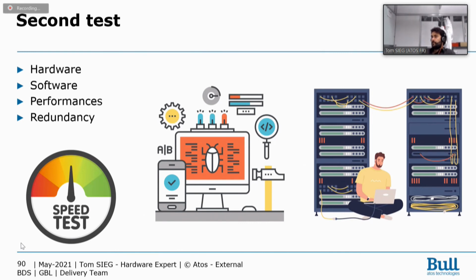Because, for example, if you have a server compute node, I don't know, an air cooling compute node going at the maximum capacity, generally it's 2.2 kilowatts or 2.4 kilowatts. If you lose one PSU on a system that has a 1+1 PSU redundancy, the other PSU will take all the power consumption. So the ports on the PDU will get all the power consumption and your infrastructure has to be able to maintain it.